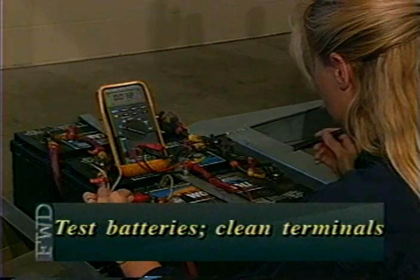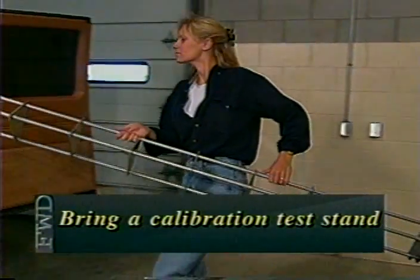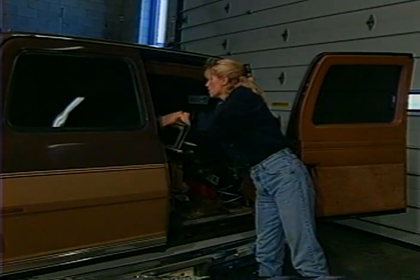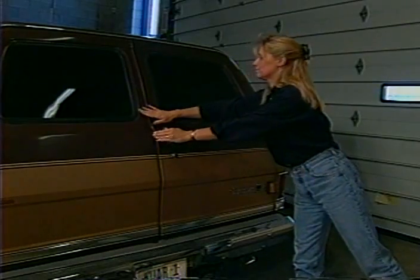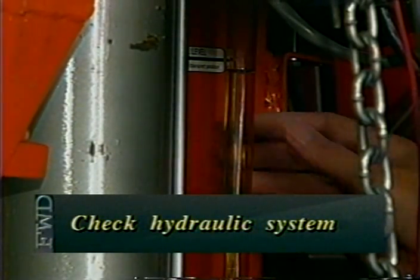Test all of the batteries and clean the terminals. Bring a calibration stand that can hold the maximum number of sensors used on your FWD. If you don't have a calibration stand, you have to get one from the manufacturer. Check the hydraulic system for leaks, and perform any needed maintenance.